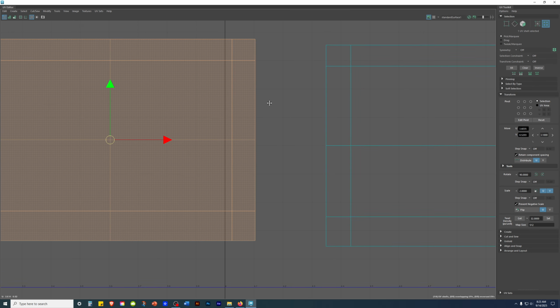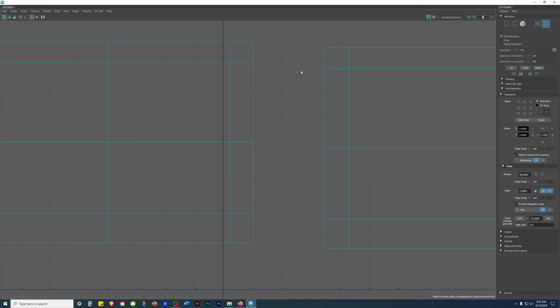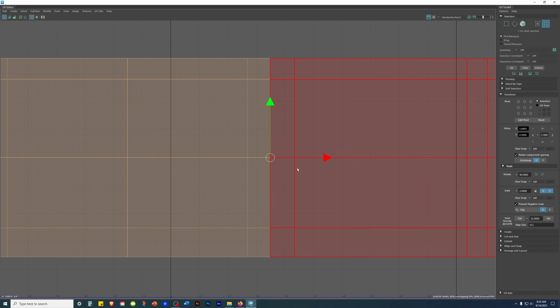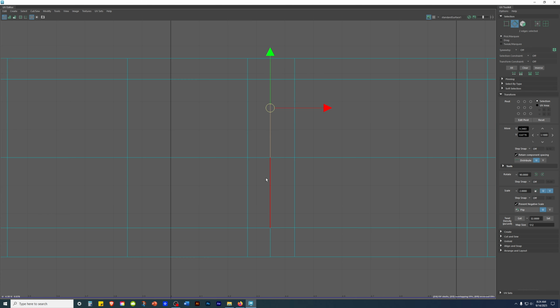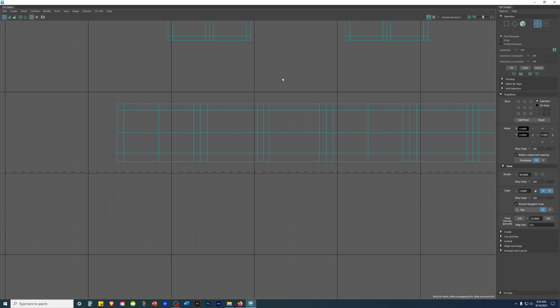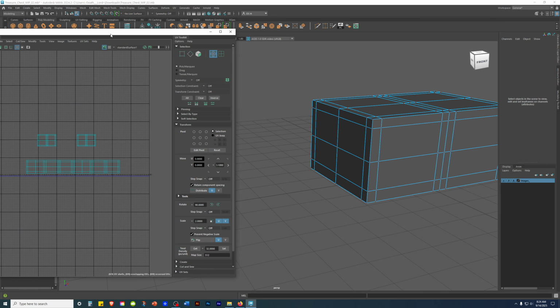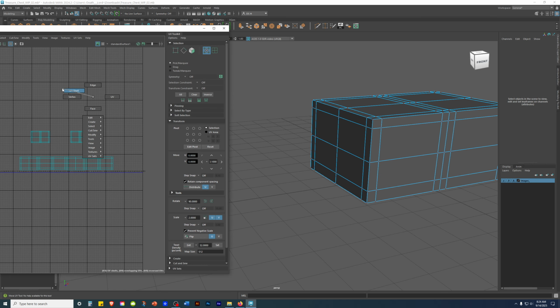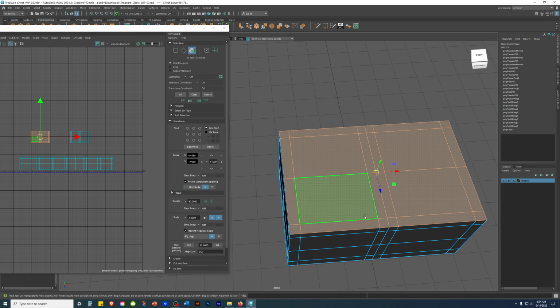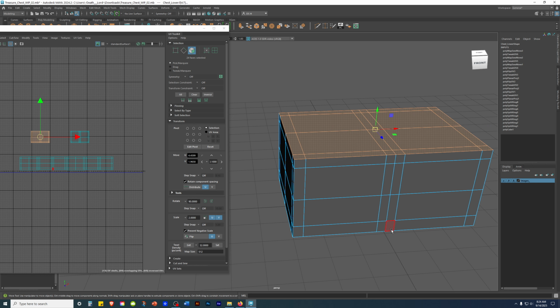Zoom in, zoom in, zoom in. Press right click, UV shell, grab the shell, press D as in David, hold V as in Victor, snap it there, press W to get out, hold V as in Victor again, and snap it, right click, edge mode, grab, grab, grab, grab, shift right click and hold, move and sew, good. Face mode. Okay.